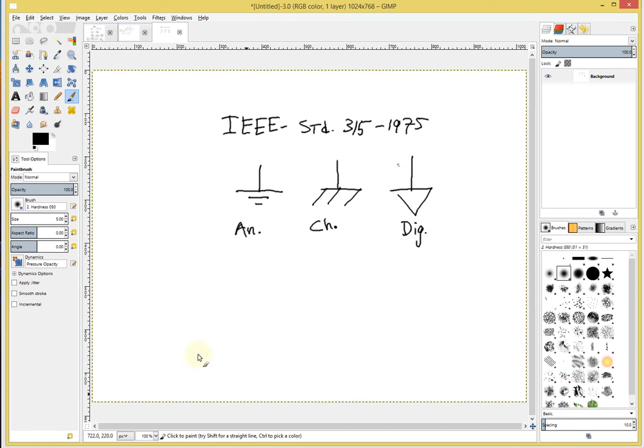The addition of yet another symbol custom made to mean ground seems kind of silly to me, and it leads to confusion because a lot of the professional EDA tools actually use the same symbol upright to mean the positive side of a power source, which is VCC, which is the same as this, which is the same as, sometimes, the arrow pointing this way.